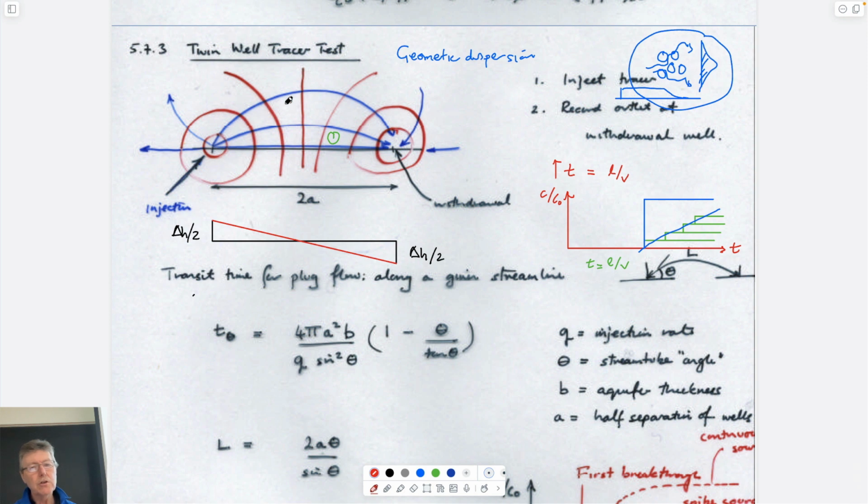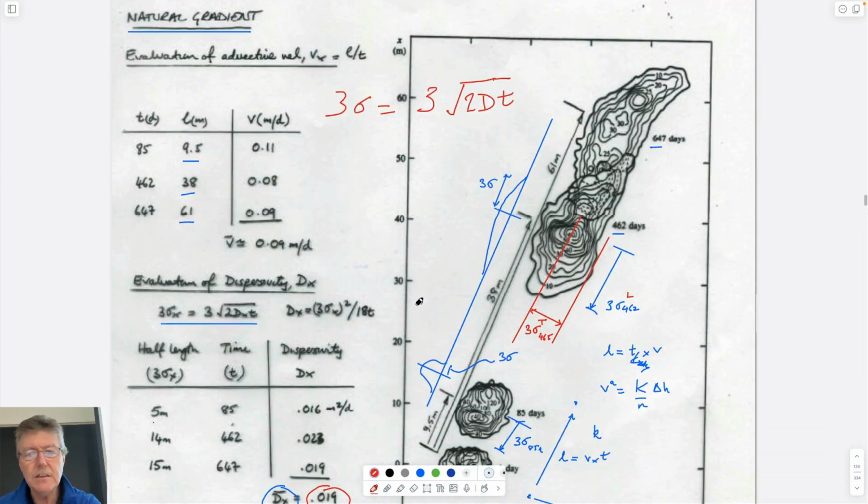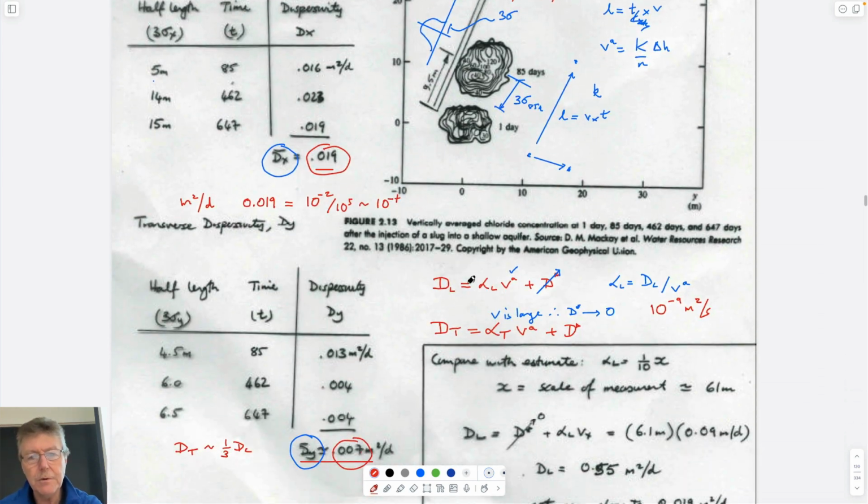And also because you're forcing the fluid to flow at higher velocities than you expect, you're probably introducing more dispersion into it than is accommodated in this simple term here. It should accommodate it, right? If you're doing it at a forced gradient, you measure the dispersion, it should account for the higher velocities you're using, but in actuality, it doesn't. And so it turns out to be not very good for that.